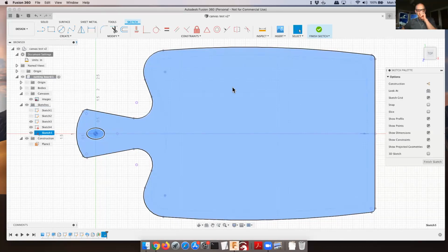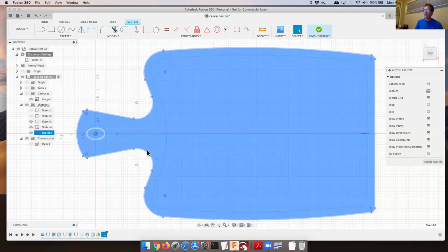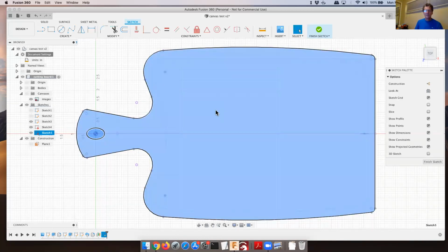So when you did that, it didn't select your groove, because it just showed the path. Yeah, it just selected the profile that it saw in that mode, because I selected the body, the entire body. There's different selections you can make to do this kind of thing, but if you make a complicated assembly in Fusion 360, you can then break it down and make one sketch using projections for each piece you need to cut out on the laser.